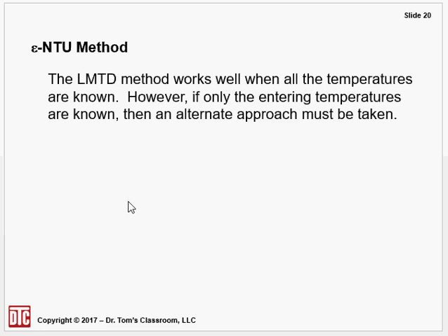This method is for when all the temperatures are not known. The LMTD method works great, but you've got to have all those temperatures: both inlets and both outlets. For problems in which you only have the entering temperatures, you need a different approach. You could try to use the LMTD method as textbooks say, but it would be an iterative process and might not converge very rapidly. So this is definitely a considerably more straightforward approach.